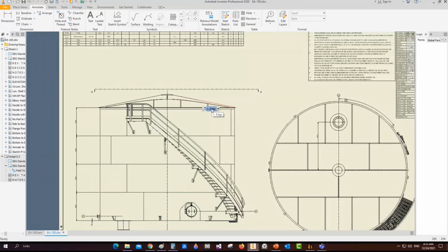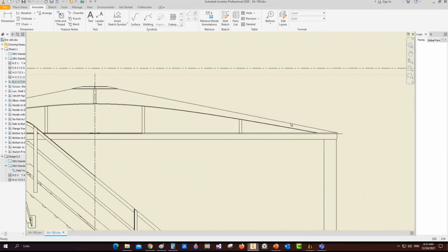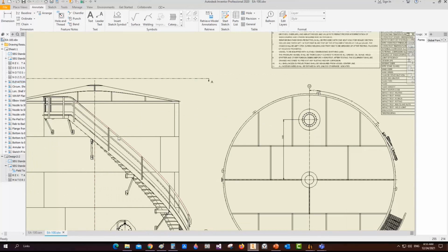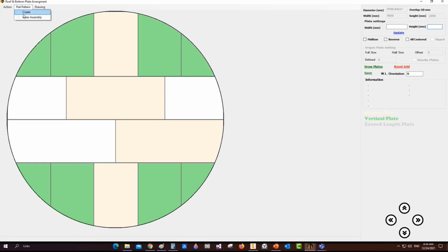to create it, actually in fabrication, we create the actual dimensions of the circle, which includes the tilted line here, or this sloped line length as the radius of the circle. After that, make the arrangement of plates. After making that, we make a slice cut and to get the conical shape. Okay, so from here, let's create the flat pattern.